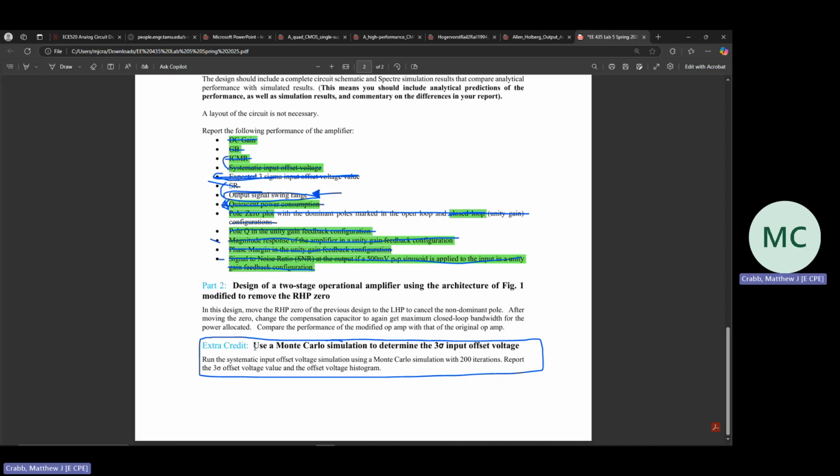Then for each simulation run, it will sample a value from that distribution or distributions. So basically, it'll randomly generate a new circuit each time based on the expected statistics of the components to simulate with. And you can run like 200 simulations, and then you can look at the statistical characteristics of your design.